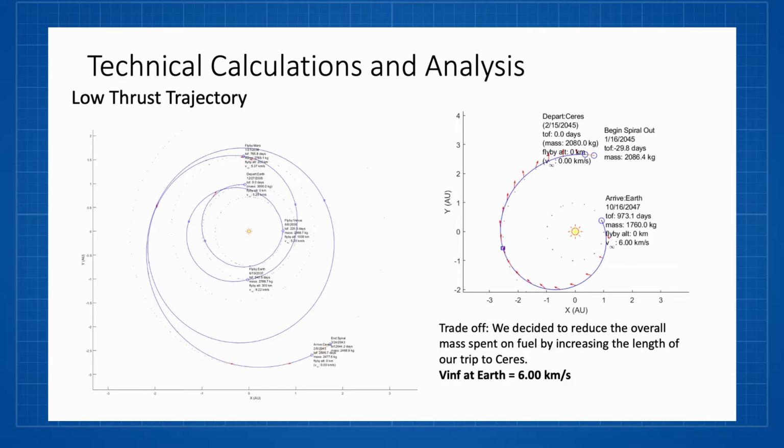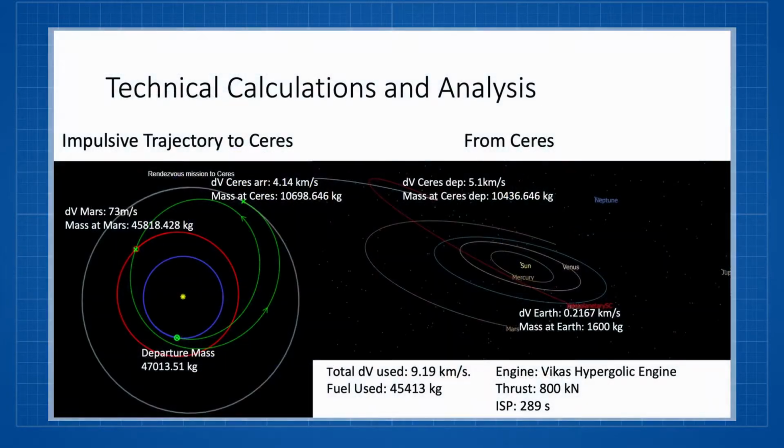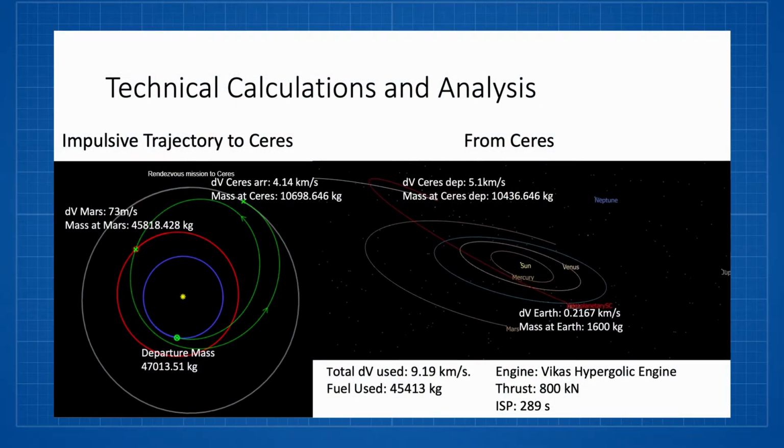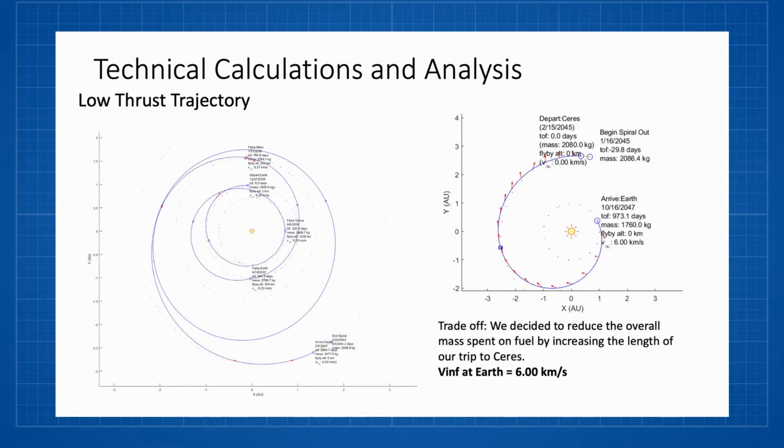After consideration of each trajectory option, the hybrid was selected. While the impulsive trajectory was significantly faster than the ones containing low thrust, the cost was an infeasibly high amount of propellant mass to complete the capture of Ceres. The low thrust trajectory, on the other hand, was very feasible, but due to time of flight constraints, the hybrid was selected over it to save time during Ceres capture and during maneuvers around Ceres.